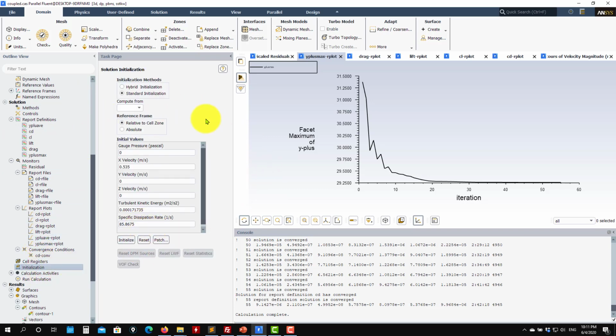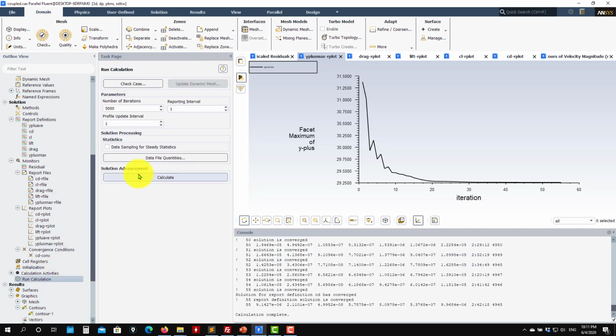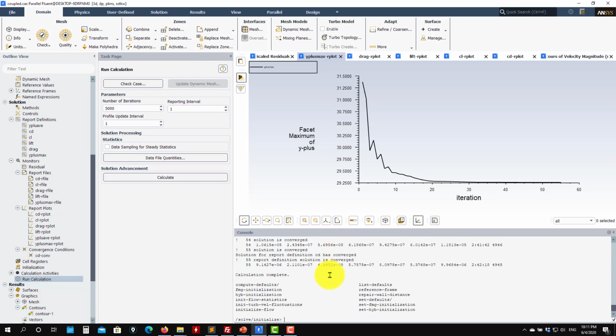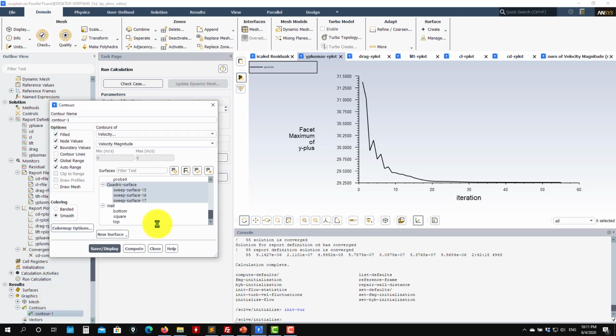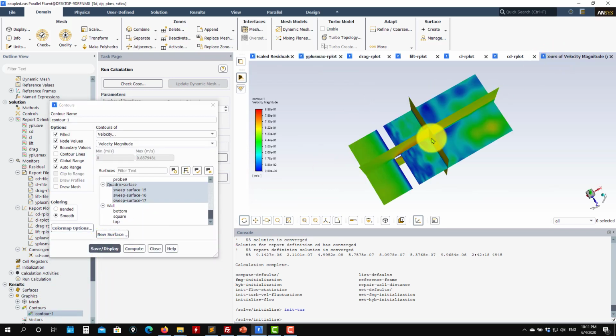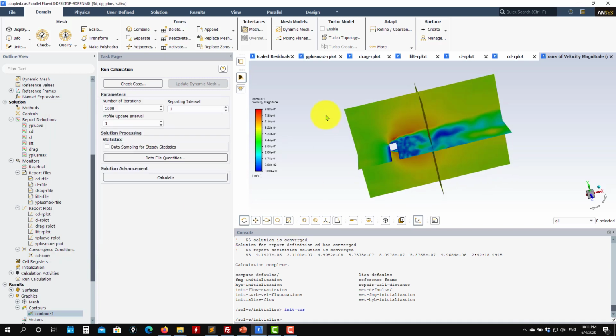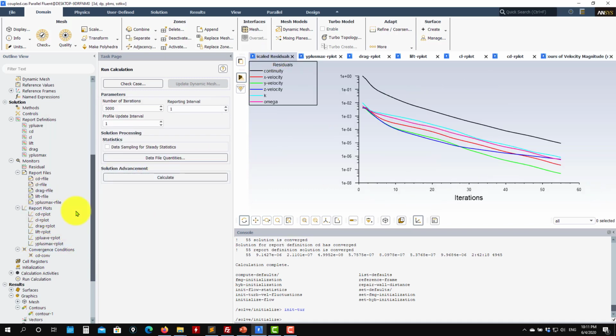So you can go and initialize again, or you can restart from the solution. It's not compulsory to proceed like I was doing previously, with the interpolation. Okay, you can restart from this solution, and actually I will do that. So in this solution, I will add now a perturbation. So I have that field that is, let's see what we have. Okay, see that the field is perturbated, and starting from here, without initializing from zero, I will go and keep computing using a new solver.